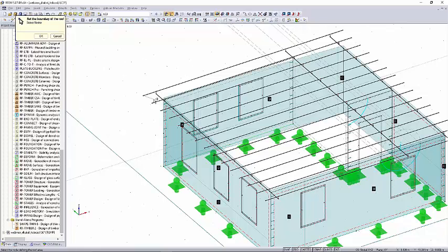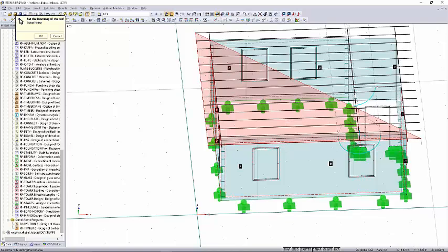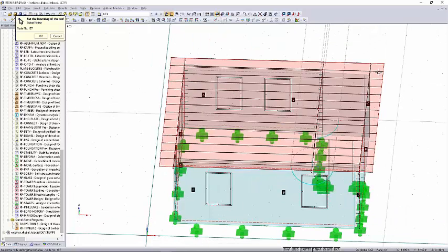Something that we have implemented pretty new, I would say for 2 years or something, is the possibility to regard the roof overhang as well. So when you pick the nodes on the outside, it will actually also regard the wind that's underneath the rafters here on the roof overhangs. So you know that there will be wind in other directions than on the top of the roof.